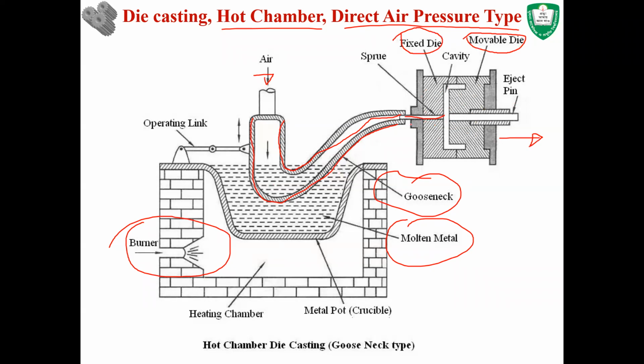Once the molten material gets into the cavity, you keep the pressure on for a certain time so that the material gets solidified. There will be a cooling mechanism present in the die, which is not shown here, so that the material gets cooled.